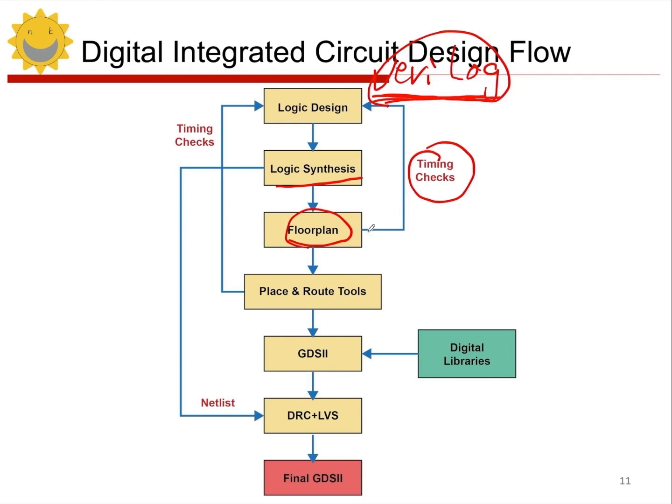This timing check is mainly to ensure that the arrangement matches our original logic design. When we described the logic using Verilog, it didn't include specific physical components, so it was in a very ideal state. After adding these logic gates, we now have physical components to consider. We need to check if this layout can still meet the original functionality.